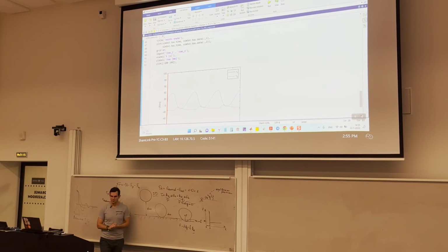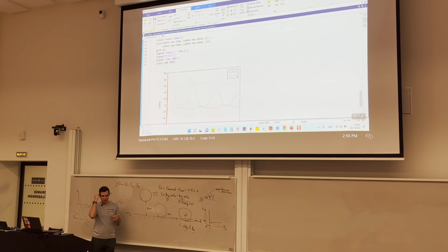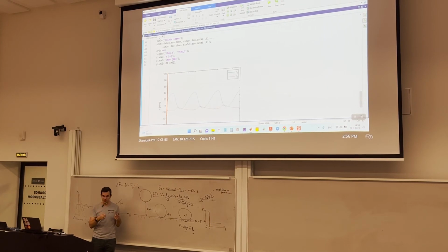But I think the most dangerous part of the controller will be the KI, because the error is constant. If we use constant coefficients, we choose the coefficients such that we follow the trajectory precisely, but if we interact with the world with the same coefficients, it will produce just a lot of torque if it hits an obstacle.